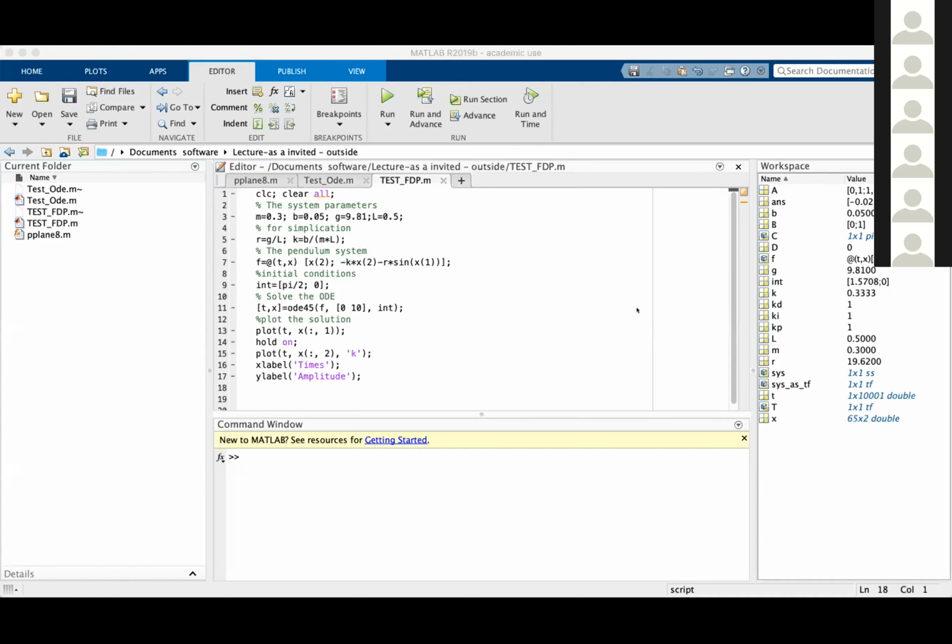Wow, nice. So you can see that even when we don't have damping in the system, there's a huge oscillation. That's why damping is very important in the system. If you see the mass spring damper system, because of the damper, as time progresses, the system is decaying exponentially. But in this case, if there is no damping, your pendulum system will not stabilize. So now this is what we have seen from the numerical simulation.